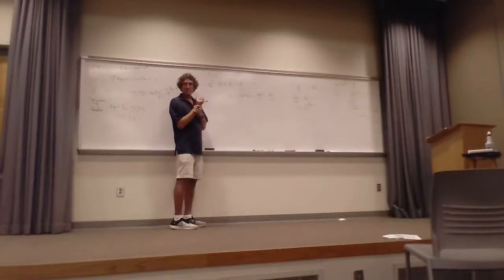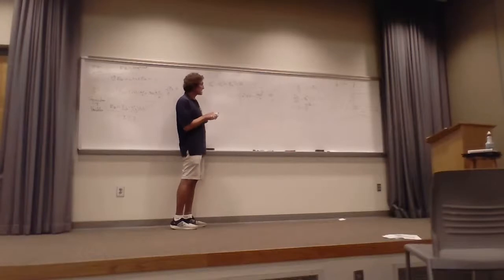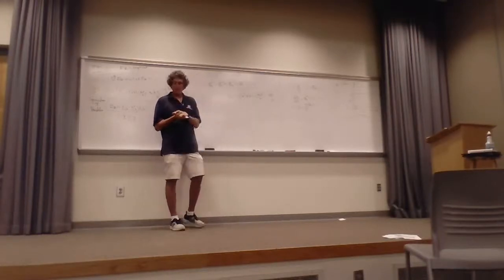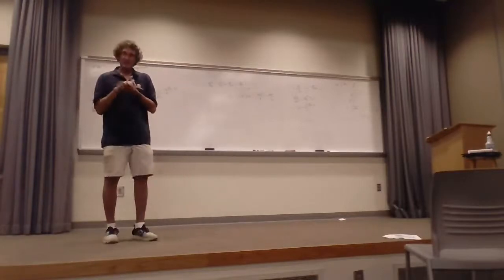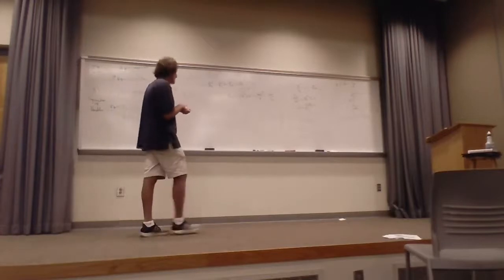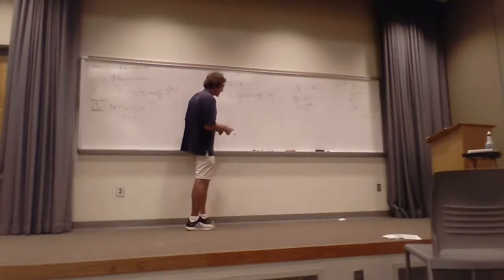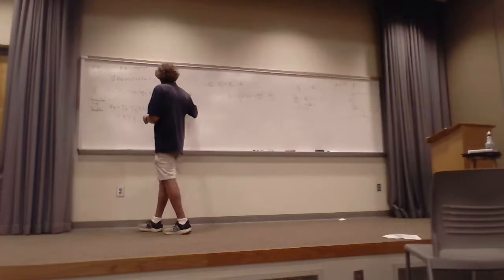You with me on this? This is perfect. Everything over here depends on the frequency or on the value of m or n or a. In other words, it doesn't depend on some unknown. All this is known. You normally excite a waveguide at a known frequency, you know how big it is. And if you assume it's filled with air, then mu epsilon is 1 over c squared. But y'all with me on this? Here's the next step of this mystery. Let's do it here.